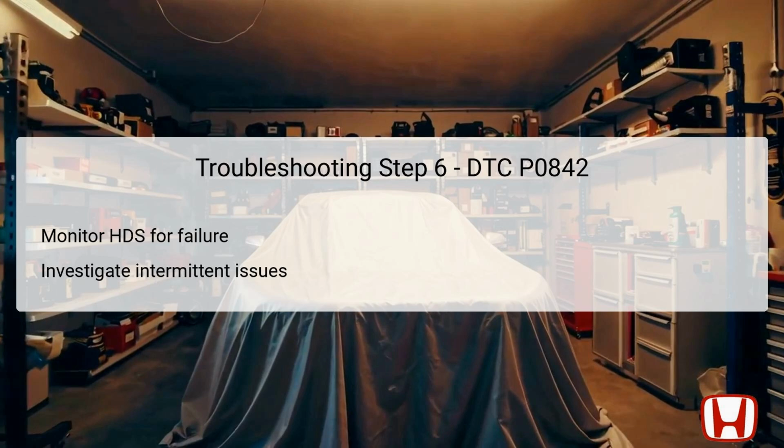This process involves careful inspection of the wire harness and connections, as wiring faults can lead to erratic switch behavior or false readings. The focus should also be placed on ensuring that all electrical connections are clean and secure, thereby eliminating common sources of intermittent faults.